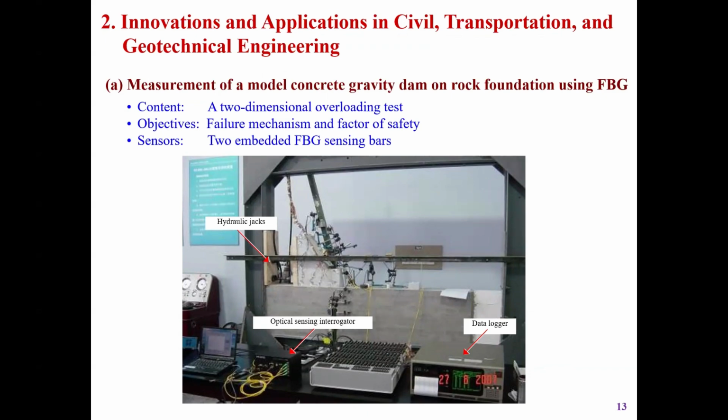The optical fiber sensors measure directly strain or temperature. But in many cases in geotechnical engineering, we are more interested in other parameters: deflection, loading, displacement, cracks, or pressure. We are interested in a wide range of parameters. Here is one way to use the strains measured by the optical fiber sensors to find the deflection of a concrete dam in a model test.